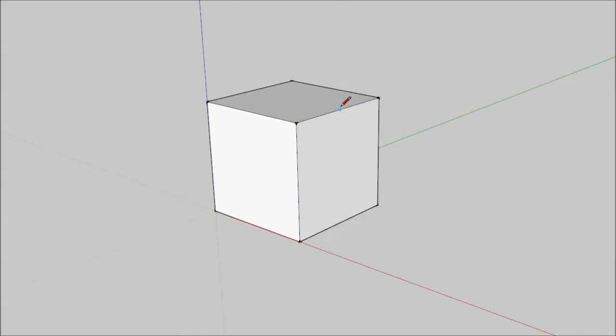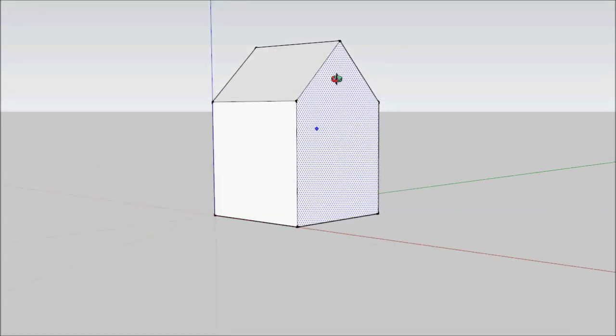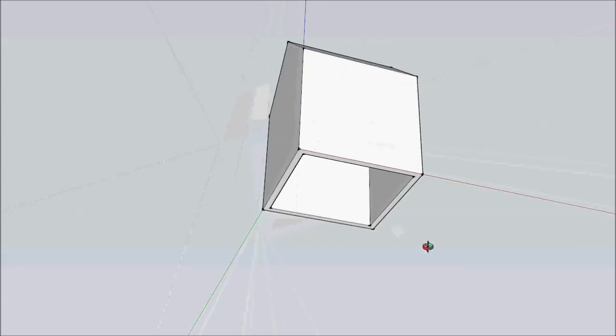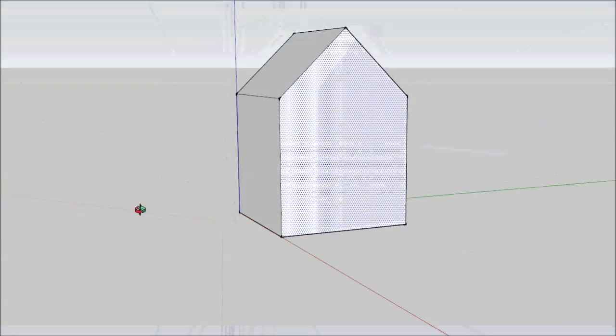After you draw and push it up, you gotta make the roof. I'm gonna use the move tool. I'm gonna type in exactly how tall I want it to be. So now I have a rough outline of the house. To make the bottom of it, we use the offset tool, figure out how big the walls are. Here, separate those, and then this middle portion we're gonna push up inside to hollow out the house. So now you have a hollow house with a roof.